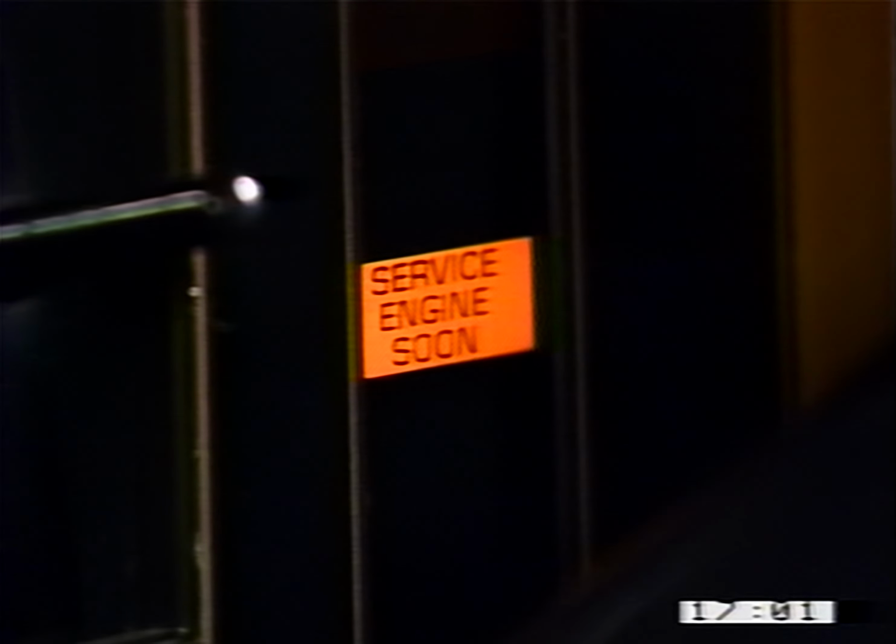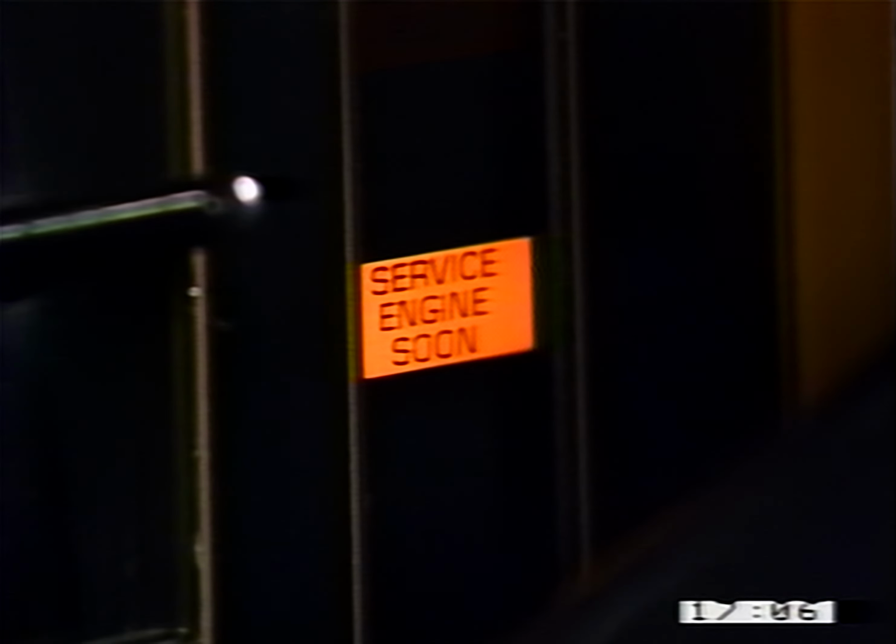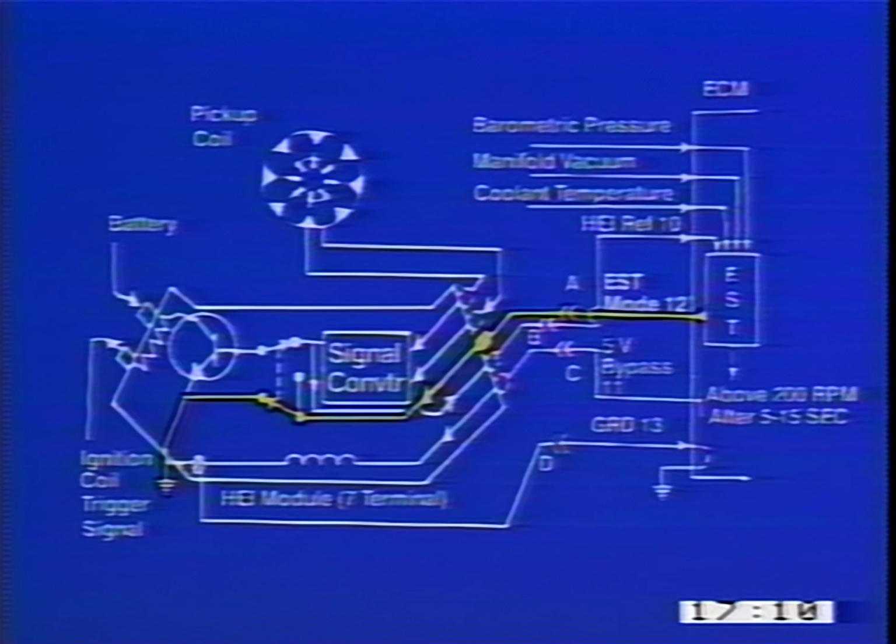The ECM monitors the EST lead, ensuring that a high-low signal, called a signal toggle, occurs under the proper conditions. During cranking, for example, the EST signal should be grounded in the module and should not be able to go high. If it does, a code 42 is set in memory. A bypass circuit going open pulls the EST signal to ground during engine operation, also setting a code 42. The technician then follows appropriate diagnostic procedures.